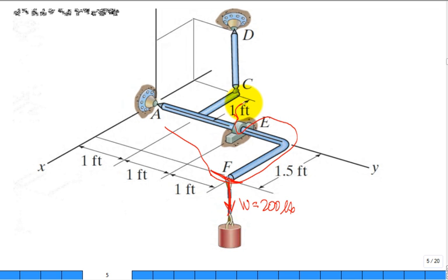Then I back out in air, and I'm going to cut through the ball and socket at C. I could come up and cut through the ball and socket at D, but then it just makes it longer. And let's cut through C. We can continue the discussion about what happens if I cut through D. And then I cut through air, and then I cut through A. And now I know it's a circle in 2D, a line in 2D, but in 3D, think of it as a surface to isolate it.